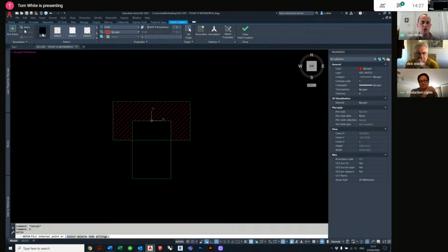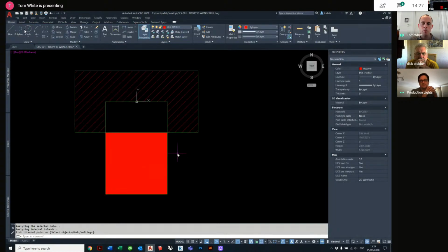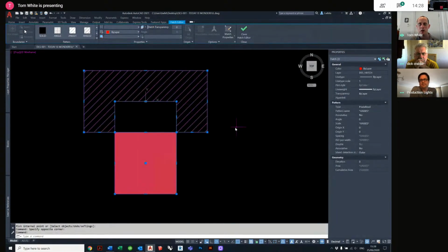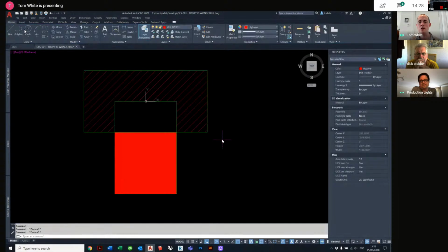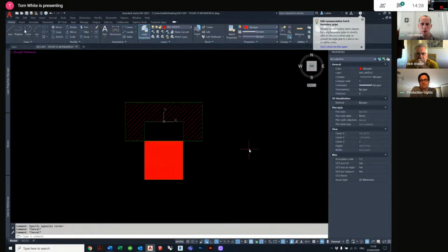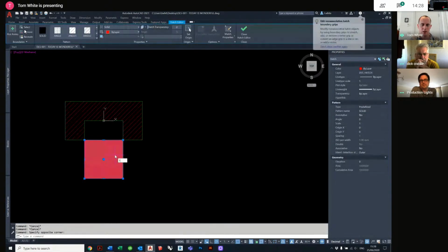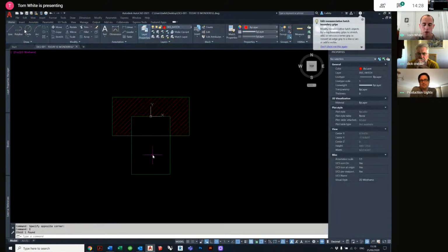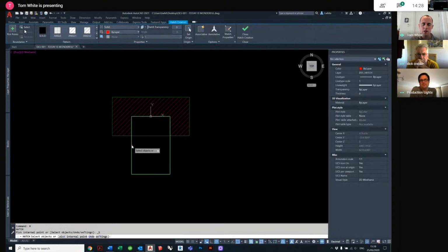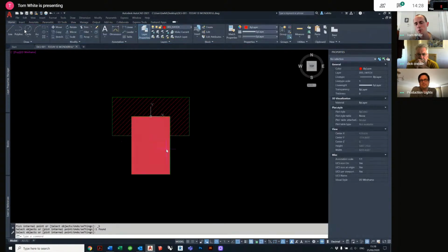So in this circumstance, I've done a solid hatch pattern, and I've picked the point here. They're both deemed, I believe, yes, if I select both of them, they're both deemed a hatch, but visually a hatch can be anything you desire. In this circumstance, it's multiple lines at a 45-degree angle, and in this circumstance, it's a solid fill. If I delete this object here, the reason that I would use pick point in comparison to select is that if I do select and just select one object, it doesn't do what I desire.